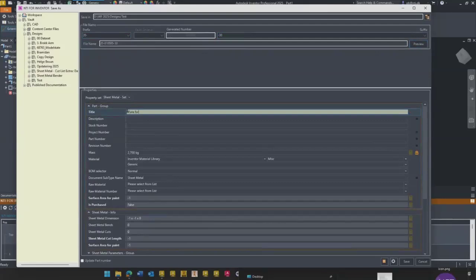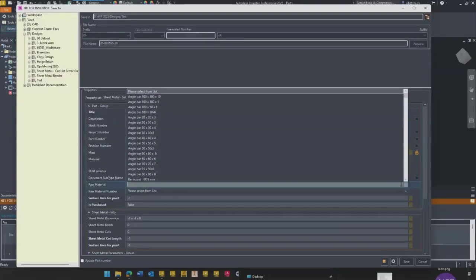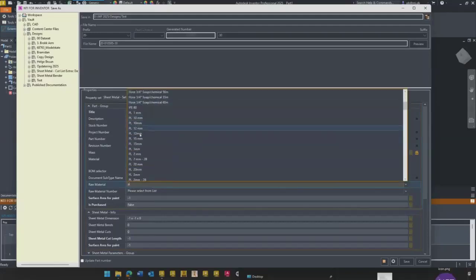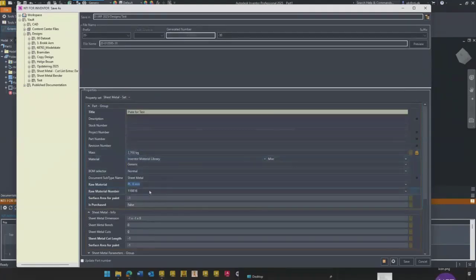Again, my property editor is built into this number generator. So it will appear when you're saving your files, to remind you to fill out different lists or different properties. It's also pretty convenient that when you're saving you can type in your properties.